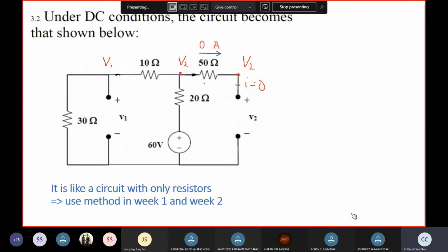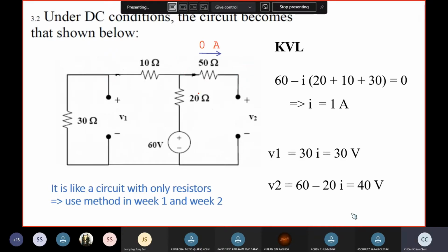So after that, you just use nodal analysis. You can find V1 and V2, right? That's one way. Any method is fine, so mesh analysis is also fine. For example, I just apply one mesh current, I, because here it is 0, right? No current. So this current is known. If you call this I1, I2 is equal to 0, which means that mesh analysis maybe is better. Just now I had two equations, V1 and V2.